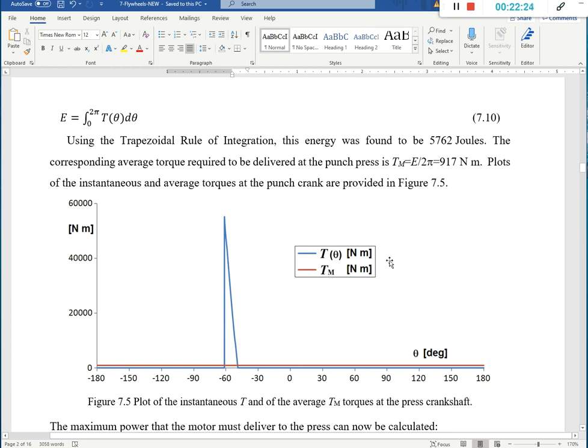Not that that will be exactly the motor power. You need excess power available. So if you calculate this to be 0.1 of a kilowatt, 100 watts, it doesn't mean that you will see on the punch press a bathroom fan size motor. It will be substantially bigger to accommodate larger holes to be punched, and also to be able to accelerate the machine quickly from rest.